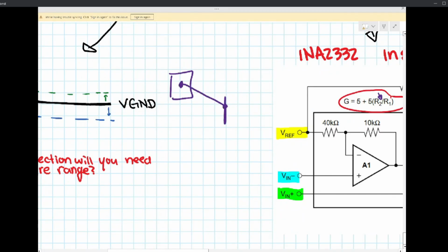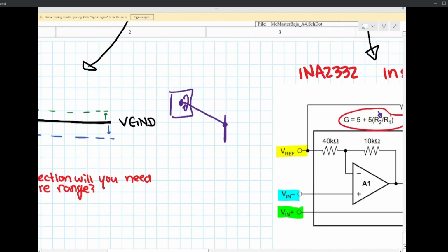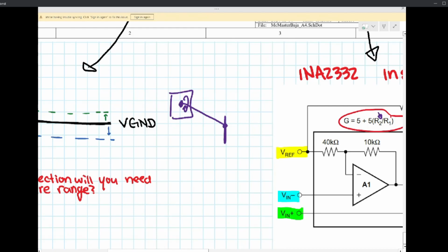The engine is going to supply some sort of moment, your wheel is going to try and resist that. Say you're starting from 0 and accelerating, and your axle is going to see some torque going forward. It's going to be some amount from whatever the engine supplies, and then you get to your cruising speed. You're not really going to see any additional torque other than what's already being supplied in the system.